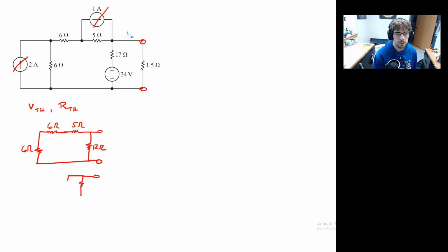And this is the advantage to having done that source transformation first: this should look familiar, as we came up with that earlier. Okay. And so we get that the Thevenin resistance in this situation is 17/2 ohms. Remember, two resistors of the same value in parallel, the equivalent resistance is if you cut it in half. Now, we could have gotten that doing the short circuit as well.